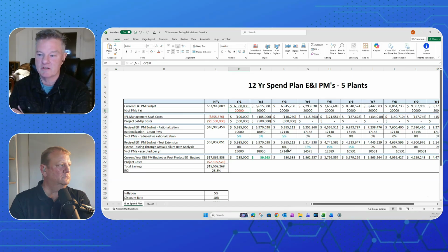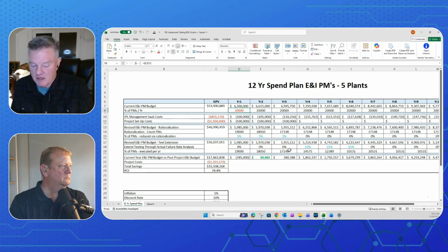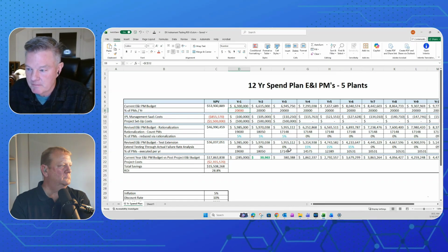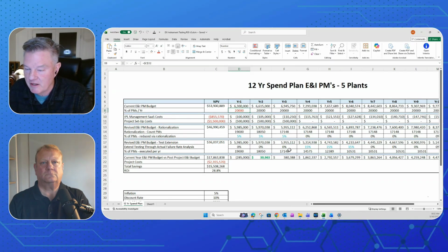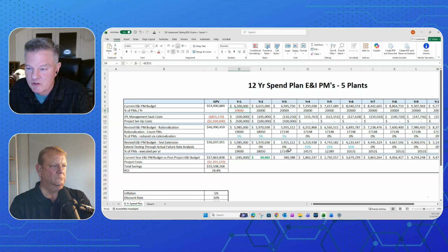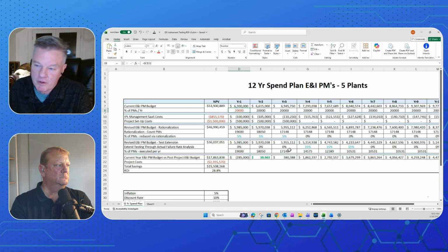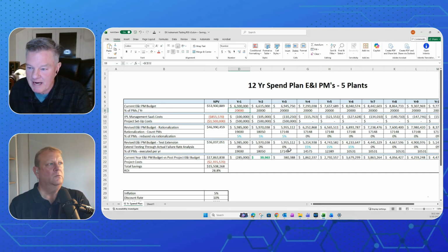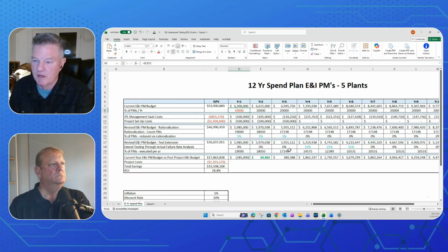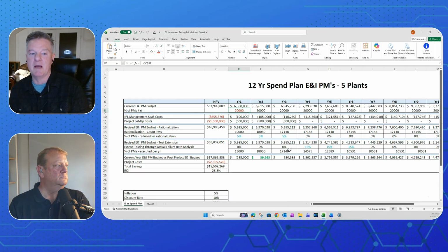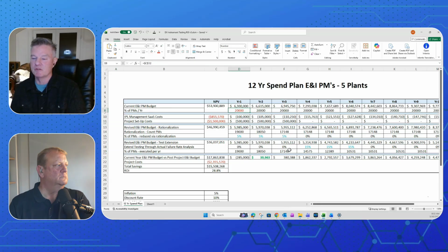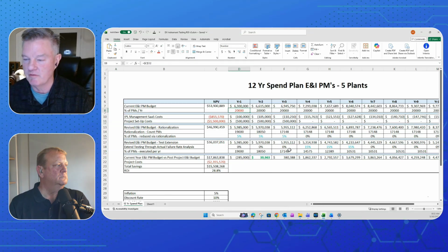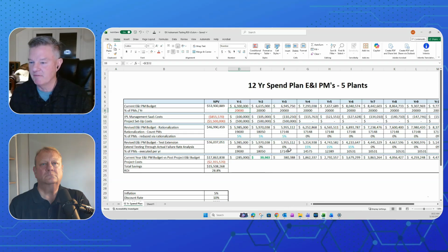We run sensitivity analysis on going from 12 months to 24 months to 36 months. The CCPS document does a really good job of rules of doubling, and I would massively, highly encourage that. If the math says go straight to 20 years, well, we don't want to do that. We want to go from 1 year to 2 years, collect more data. We want to go 2 to 4, collect more data. When we start seeing higher failure rates, you're going to want to back down and say, well, 3 is the right number or 2 is the right number. You're going to want to have a clamp that says we don't want to go past 5 or 7 or whatever the number is without administrative MOC, because you can get benefits from testing.